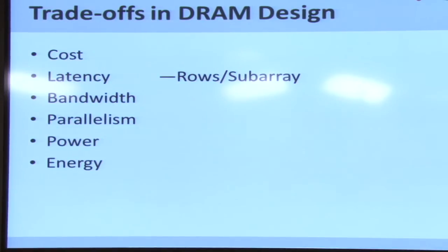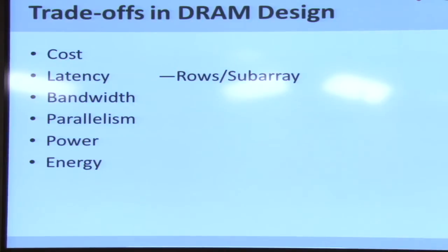It's the same thing, right? We have 8 chips in a rank. In some sense, I can give a single command to all the 8 chips simultaneously. That's the purpose of having a rank. But why would I have a rank of 8 chips? It seems like controlling each chip individually can be better, right? I can say, oh, chip 1, give me this piece of data.